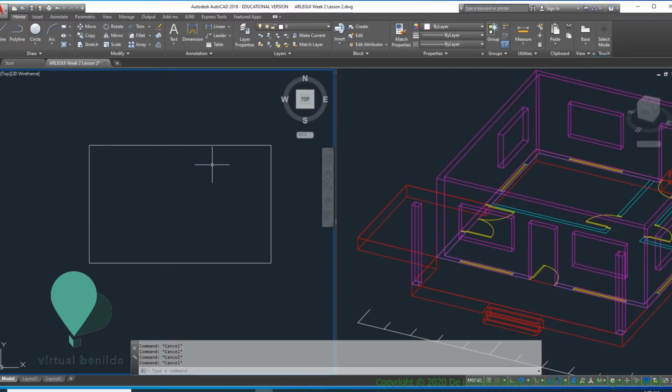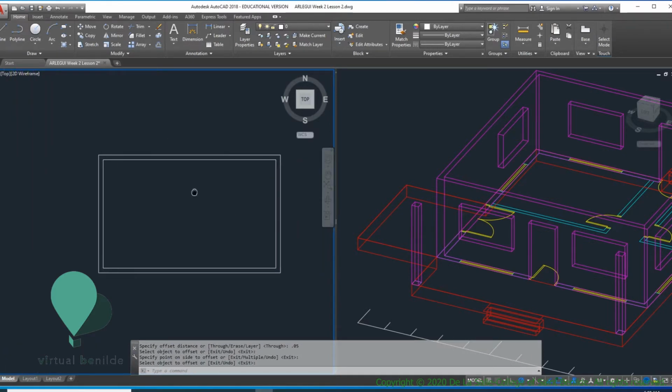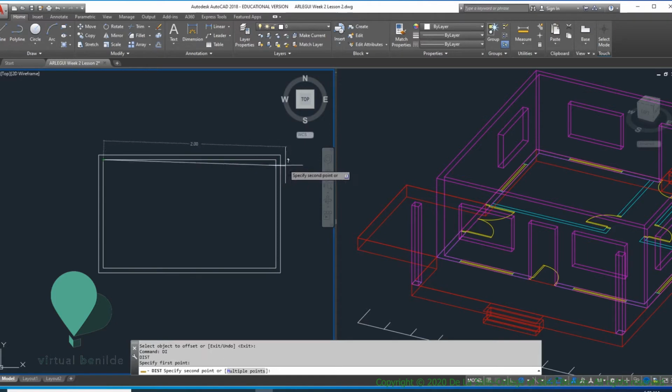I'm going to offset this by 0.05 or 2 inches to illustrate the window frame. So right now the opening would be 1.9. So that gives me a 0.95 per panel if I just want to do 2. It's almost 1 meter. That's a large window, but for the sake of this exercise, I'm just going to do 2 panels.